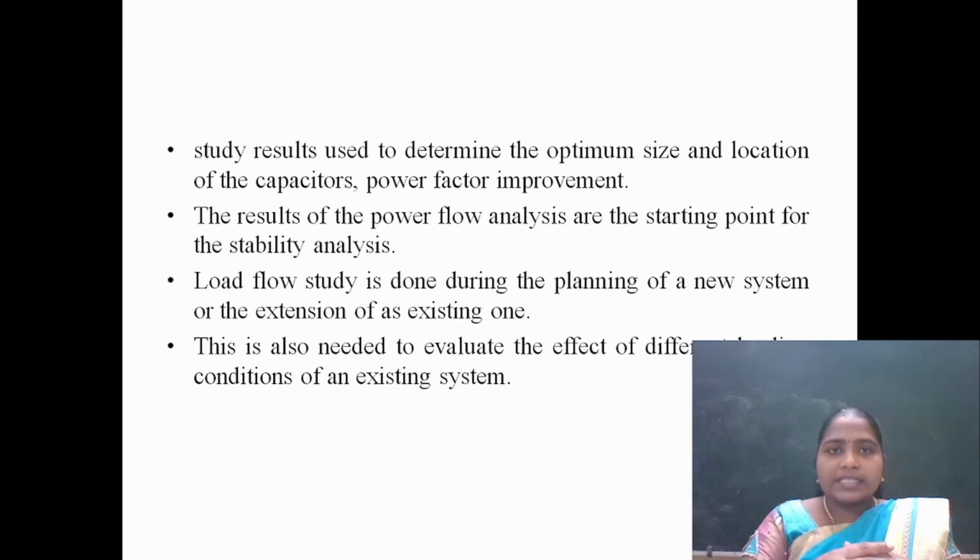The result of this analysis is to determine the optimum size and location of the capacitor for power factor improvement, and this results in the stability analysis. A load flow study during the planning of a new system is completely required and essential. This is also needed for the evaluation of the effect of different loading conditions on an existing system.